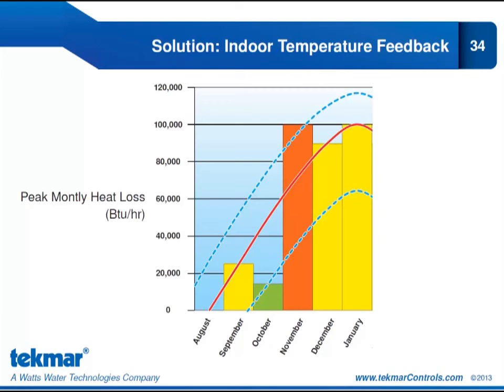So what is shown on the slide right now is a heat loss chart for various months of the year. The red curve is the reset curve based on outdoor temperature reset. And you can see this works perfectly well for the month of September. However, in October, the heat loss from my building is much lower, which means I need a lower heat supply to compensate for that loss.